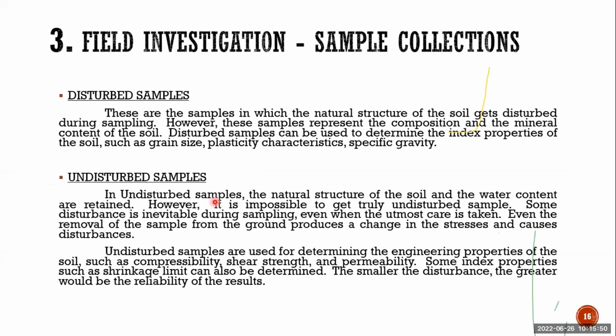Now, based on the field investigation, samples can be collected. The sample can be a disturbed sample or an undisturbed sample. For rock, forget it; I'm talking about soil. In the disturbed sample, let us say in the trial pit excavation, as soon as you excavate, the excavated material will be saved in a sample bag, labeled, and brought to the lab.